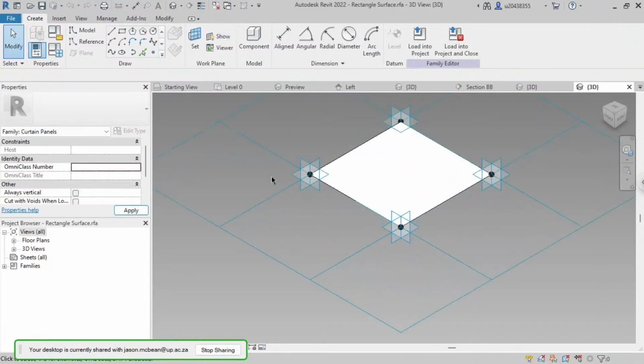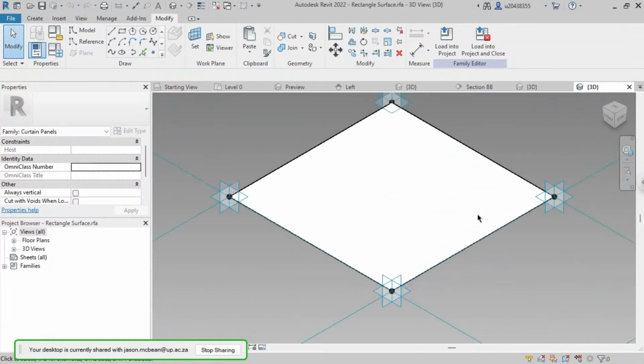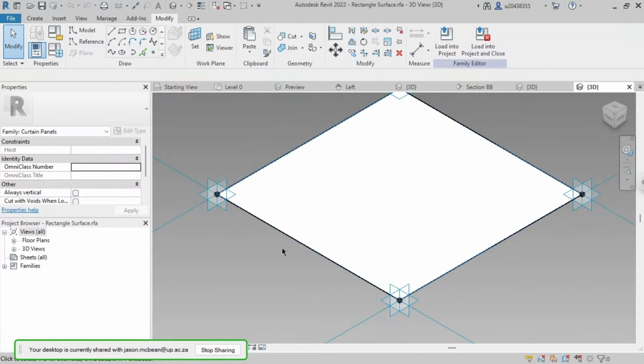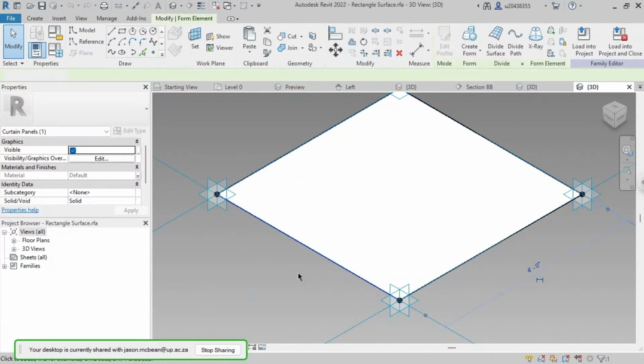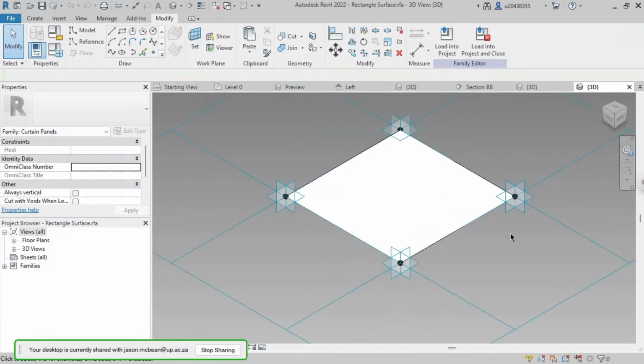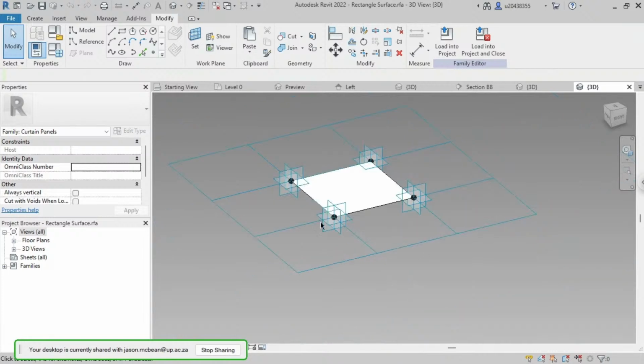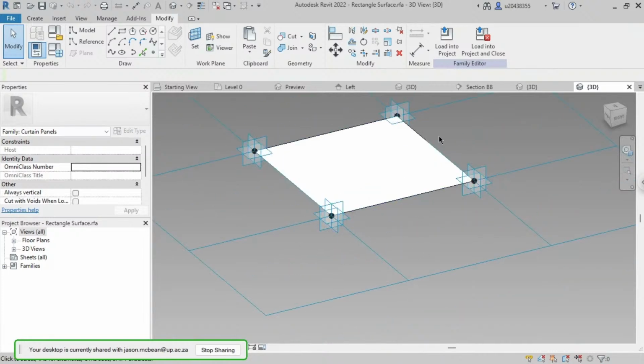You need these nodes to fill up your pattern, but I can run an extrusion along these edges with the structure, then it'll actually build that structure for me. If I press tab, you'll notice it'll allow me to extrude stuff along these. This is all it's doing. It's making these, but you can get very complex ones that have windows.